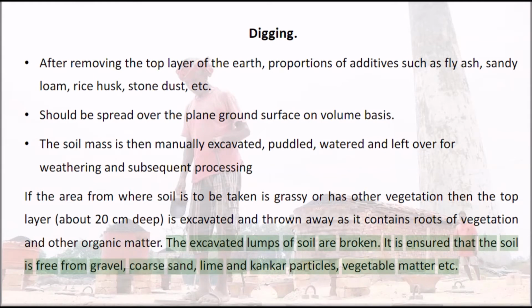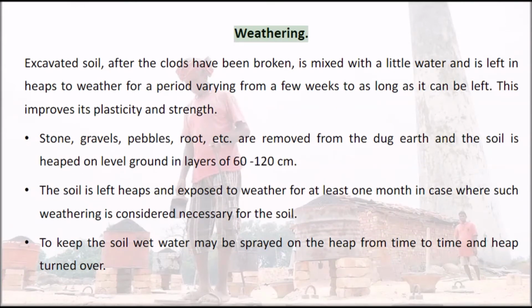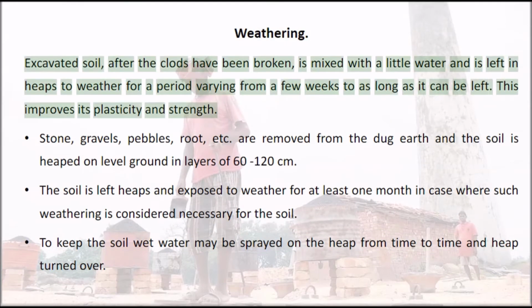Weathering. Excavated soil, after the clods have been broken, is mixed with a little water and is left in heaps to weather for a period varying from a few weeks to as long as it can be left. This improves its plasticity and strength.